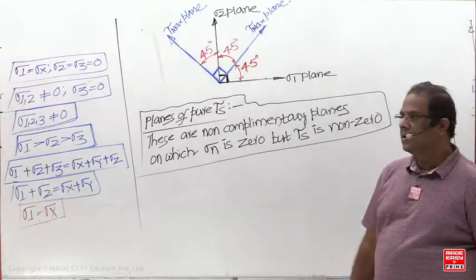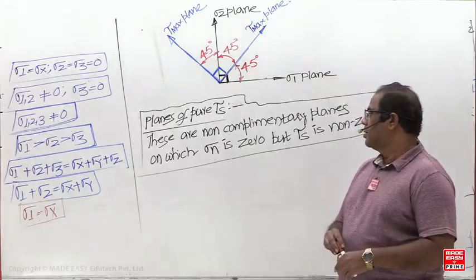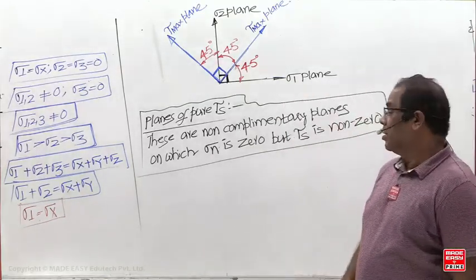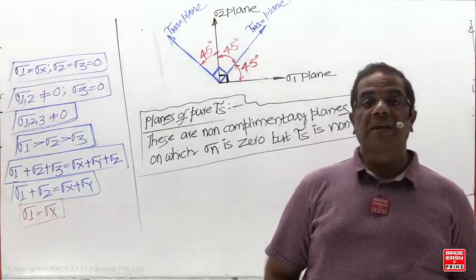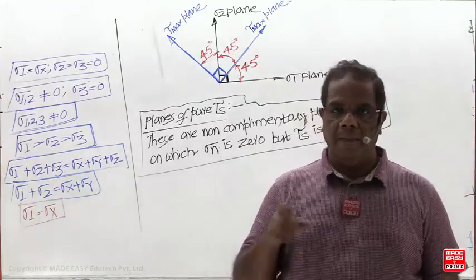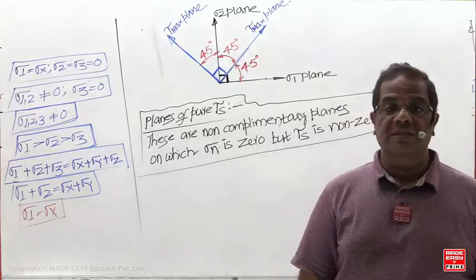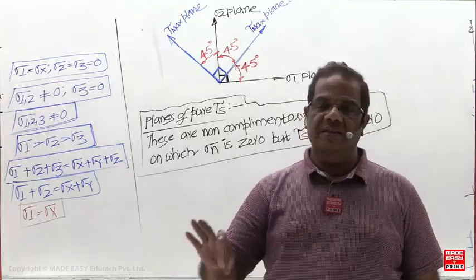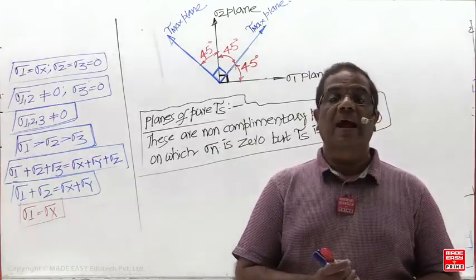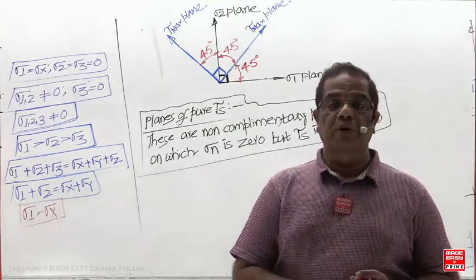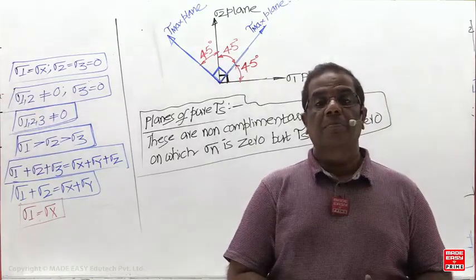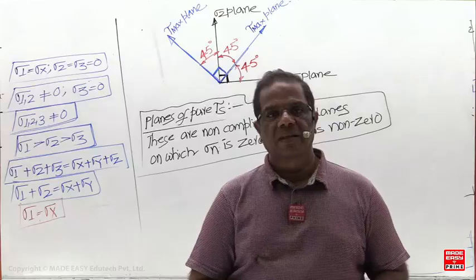Next point. Planes of pure shear stress and tau max planes coincide when sigma x plus sigma y is 0.